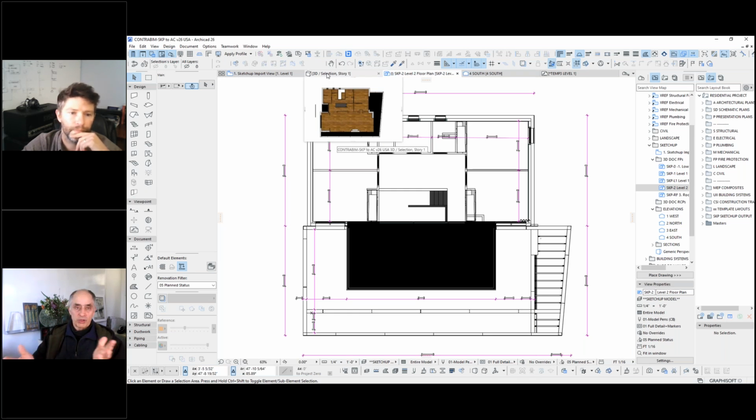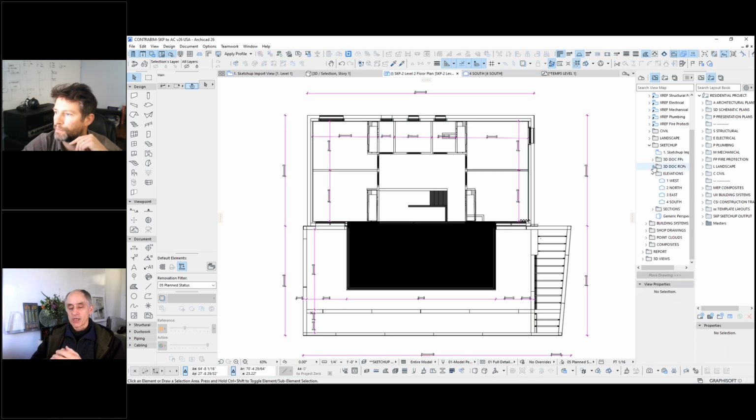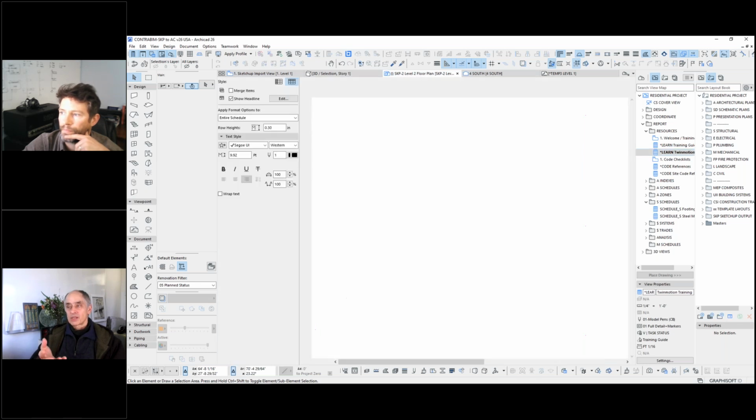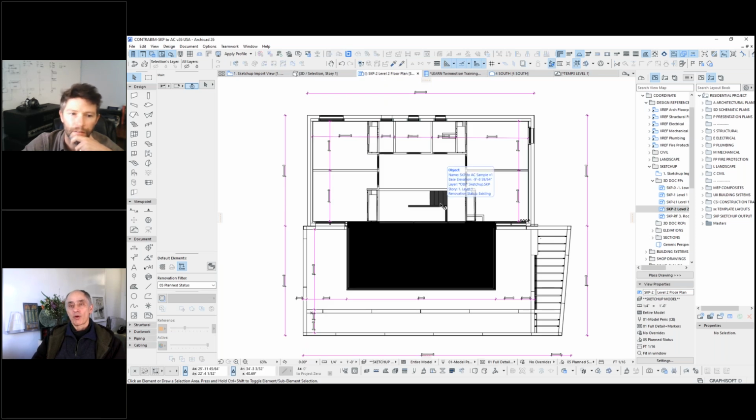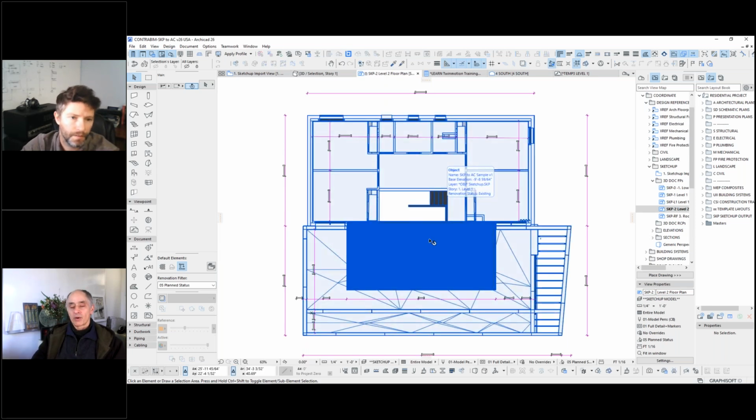So now we have something that looks in 3D like a building that's been modeled in SketchUp, so it has a certain level of detail. And you're saying we want to be able to recreate this with ArchiCAD native elements so that you can get full working drawings. So you're essentially creating a 3D document that's looking down on the plan with settings for where you're cutting. And so you're not actually having to do cutting planes, you're just telling it how you want it cut. That is conceptually quite a bit simpler. Just do this for me, as opposed to me having to drag it up or down.